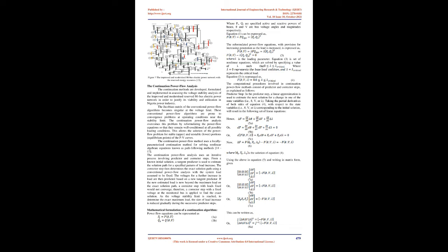The solution power voltage, PV, curve is an important element in voltage stability analysis, which can be computed by continuation power flow method. The continuation power flow method is a powerful and useful tool for obtaining solution power voltage, PV, curves for general nonlinear algebraic equation by automatically changing the value of a parameter. These solutions power voltage, PV, curves are used to find the knee or critical point of voltage stability limit of a certain bus, which is at the nose of the curve. Voltage stability limit is the maximum loading point, MLP, which is computed by the continuation power flow method.